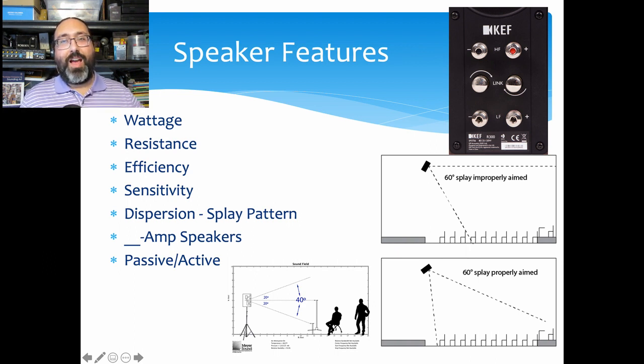Generally speaking, yes, the higher the wattage, the higher the output, but that's not exactly true because you can have a lower wattage, more efficient speaker, or you might be able to have a speaker that only reproduces in certain frequencies, which ends up adding to the SPL in those frequencies, which makes it feel like it's louder, even though it's not actually louder.